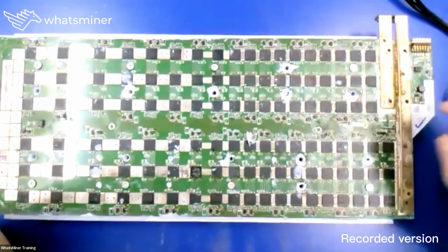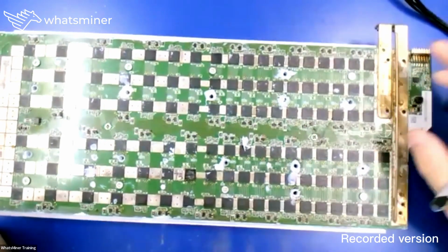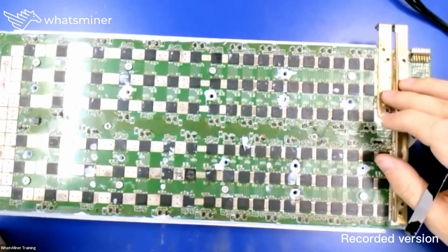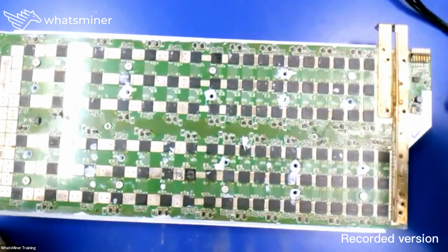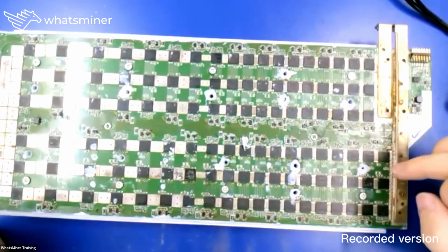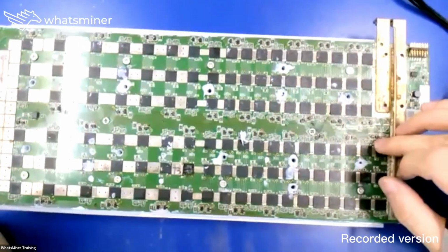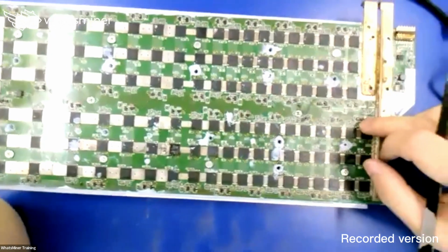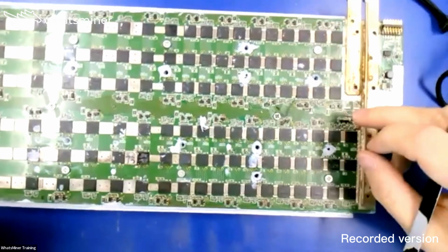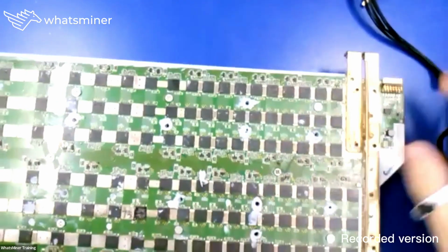And the repair method is almost the same as the M30s. Also, for this input voltage, you need to do a calculation as with the M30s. The voltage of the chip clock needs 0.15 volt, and the same for the LDO. The LDO has some difference, which I just measured. This is the main difference with the previous series. The others stay the same.